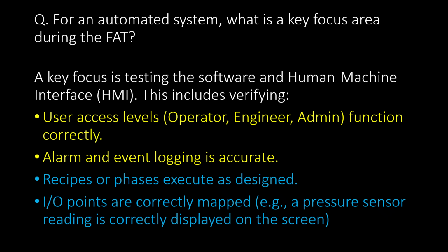A key focus is testing the software and human machine interface, that is HMI. This includes verifying user access levels like operator, engineer, and admin functions correctly. Alarm and event logging is accurate. Recipes or phases execute as designed, and IO points are correctly mapped.